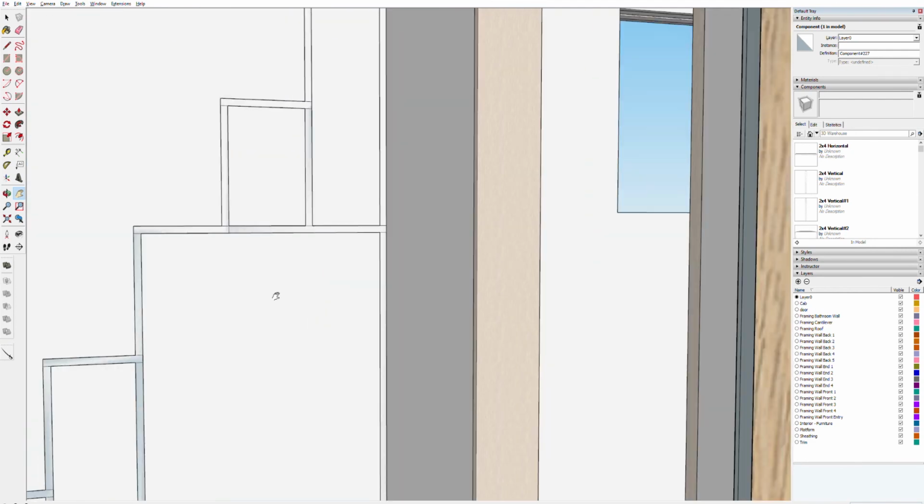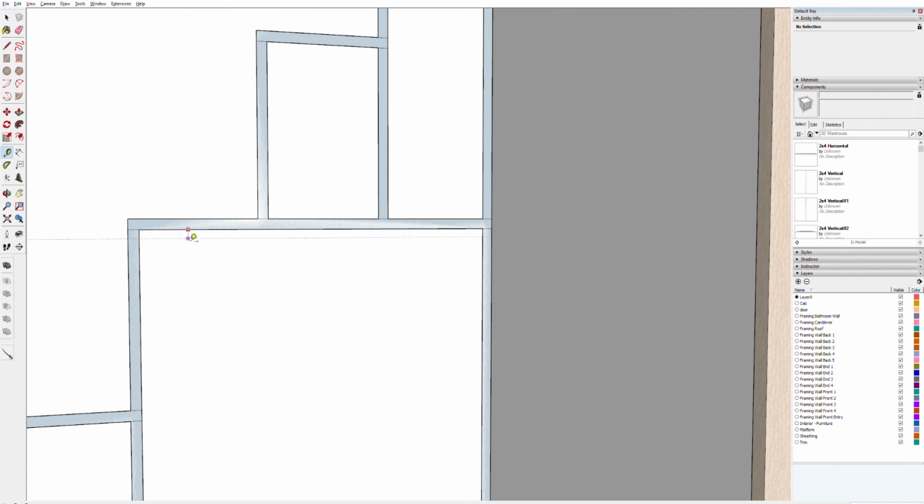So I guess what I can do is put something a little bit beefier in here, like drop this riser a little bit. Let me actually just do that right now. Yeah, I can just make this 1.5 inches. This needs to be a little bit stronger to support the weight of these stairs. So let's do this. That's 7.5. Just delete this. Yeah, something funny going on with my lines here. Don't know what it is yet, though.